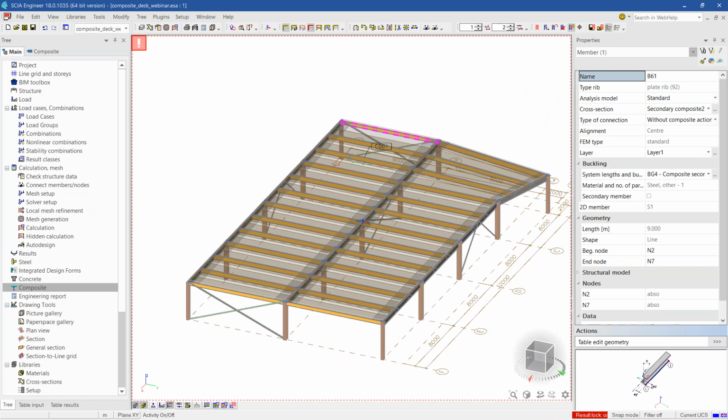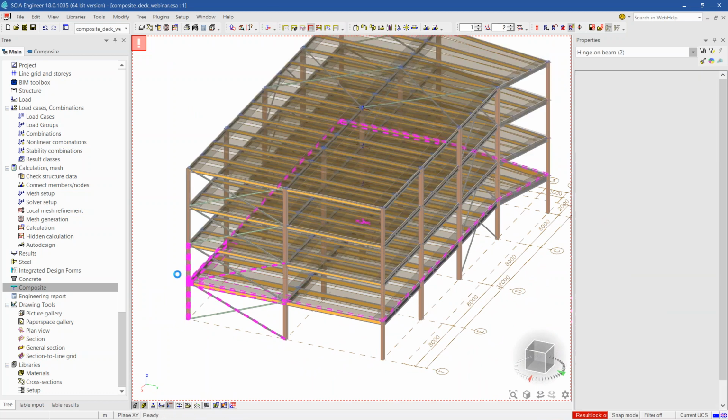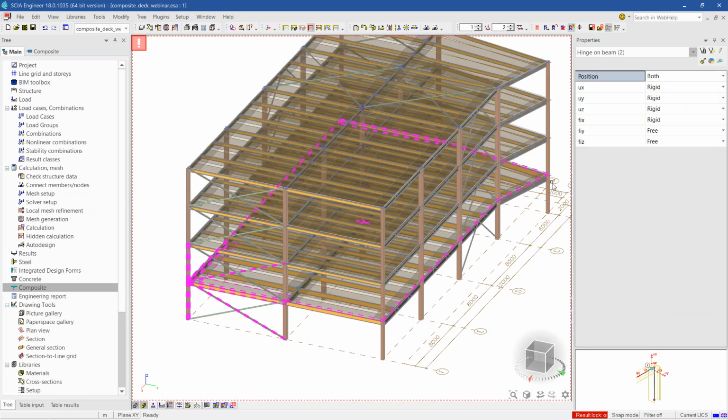You need to take also the columns, so these two columns with the floor, everything the way you've modeled it. Reduce the size of these columns, support them, simply support it here and here, and run modal analysis. And then you just export to the add-on, and there it can check footfall in quite advanced ways. But I'm not going to show this option today. We can organize a separate webinar for this.